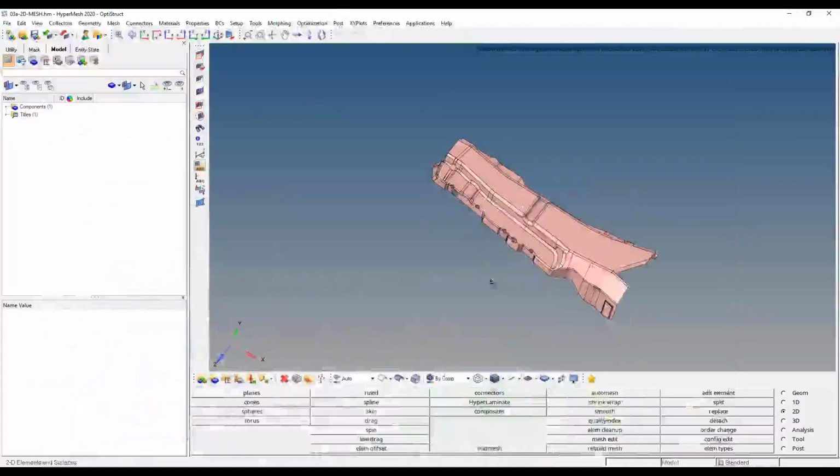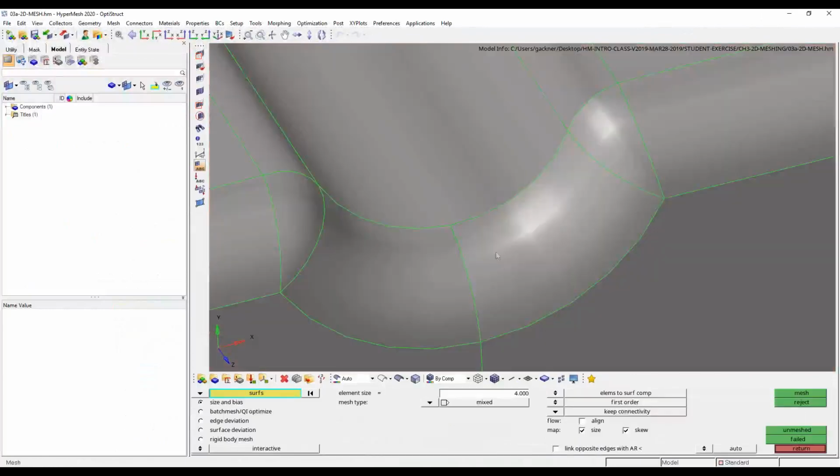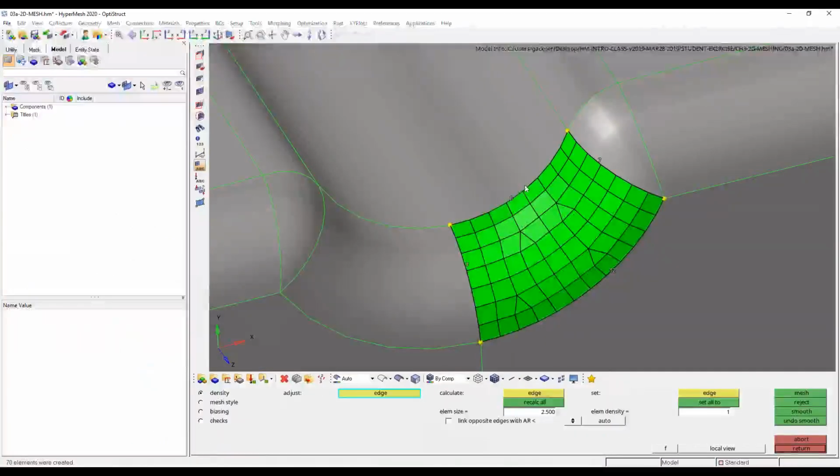So by default, we've seen with this turned off, if I take those inner and outer radiuses, like this surface over here, if I mesh it with 2.5 millimeters, it wants to do 8 on the inner radius and 12 on the outer. Those edges appear to be almost the same thing. They're partner edges of an inner and an outer radius of a surface fillet. And we know from our discussion and seeing this today that it could really make our lives easier if those are the same node density up front there.